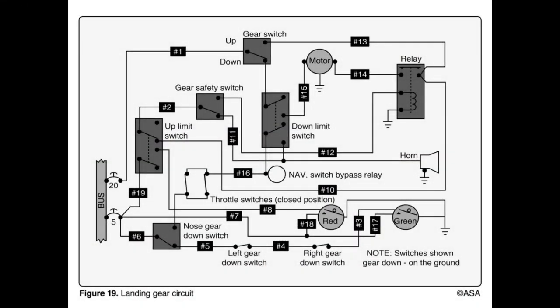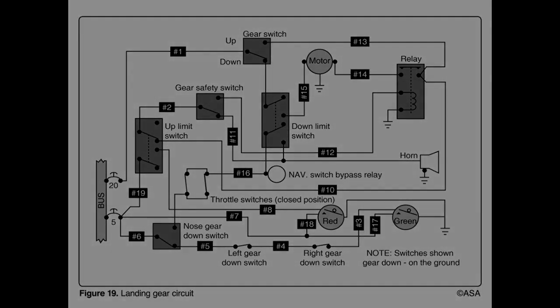Refer to Figure 19. Which repair should be made if the gear switch was placed in up position and the gear does not retract? Replace electrical wire number 12.